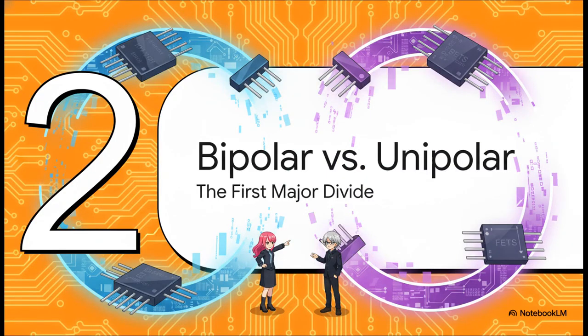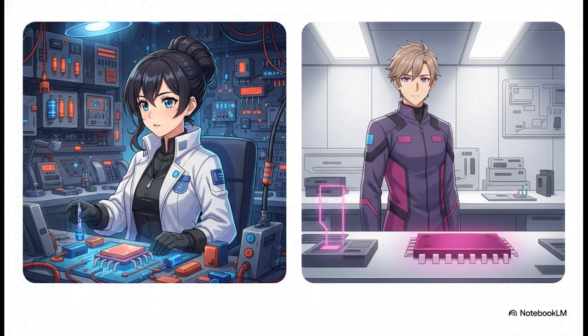Okay, so with a list that long, where do you even begin? Well, the first big fork in the road, the first major decision, splits the entire world of logic into two camps, bipolar and unipolar. And this choice has a huge impact on pretty much everything, speed, power, you name it. So what's the difference? Well, bipolar families, like your classic TTL, are built with a mix of components, resistors, diodes, and those bipolar junction transistors. They're typically fast, they're tough, but man, they can be power hungry.